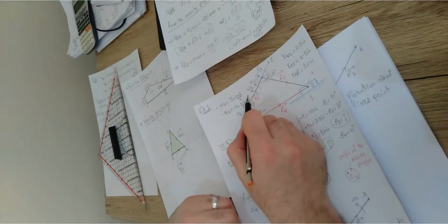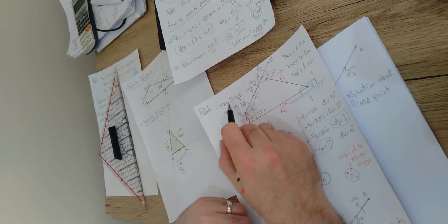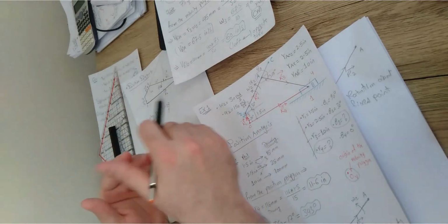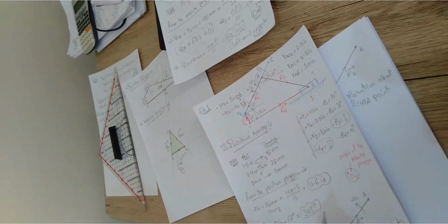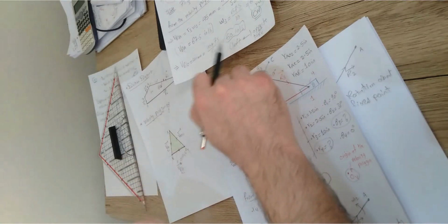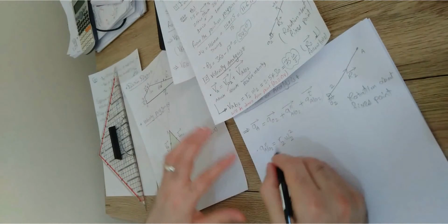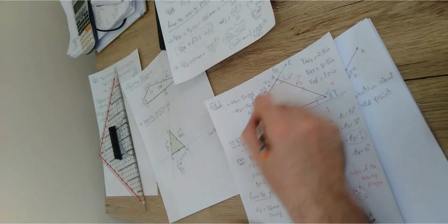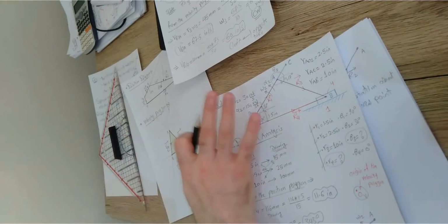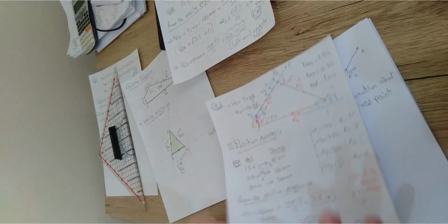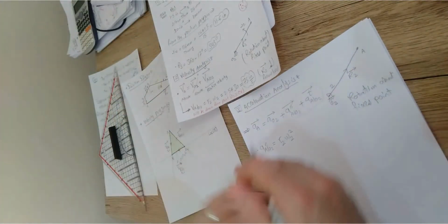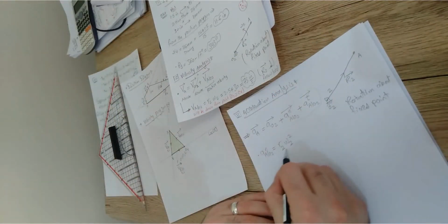This is the angular velocity of the length, which is already given as 30. Or even if it was not given, since you finished the velocity analysis, you should have a value for omega 2. And R2 is the length of this link, which should be obtained using the position analysis. So by moving to the acceleration analysis, these two data should be given.